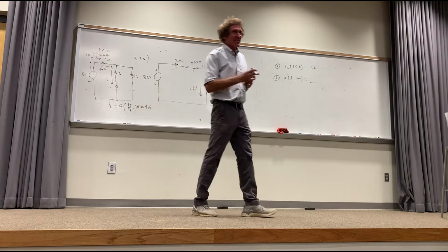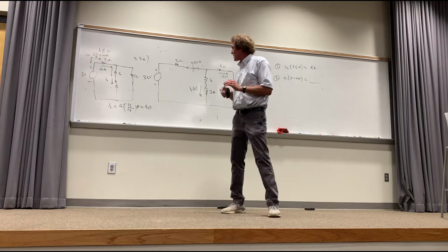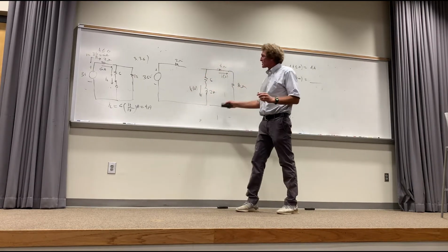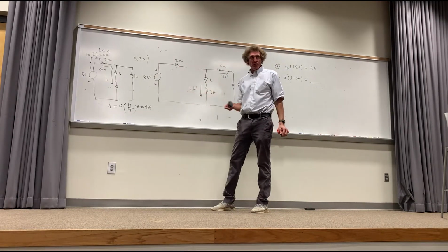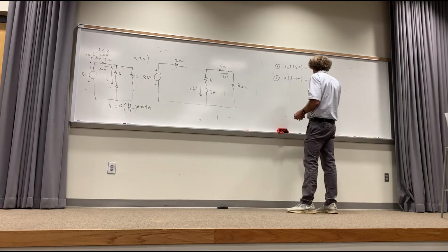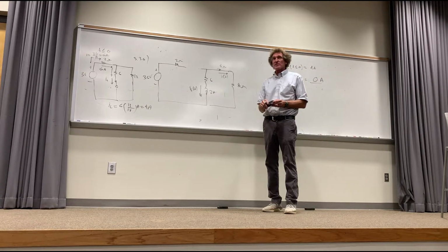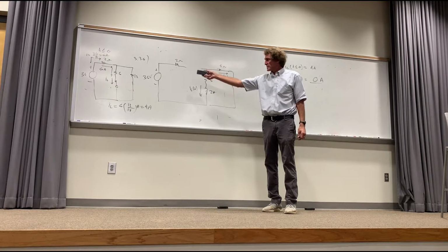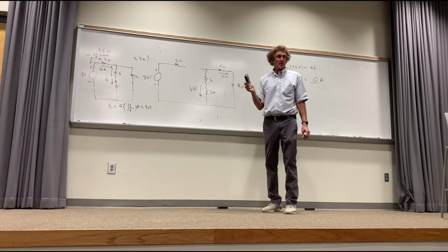I don't care. Do you have a question? Now, what is it at infinity? Well, at t greater than 0, this blows away, right? Do we have any sources in the circuit then, class? No, it's disconnected. There's no path for current to flow through that 36 volts. Effectively, it's out. So I know that IL as t goes to infinity is 0 amps. Now remember, this is t greater than 0. You all see what I'm doing here? That circuit is open, so that 36 volts has no effect on this. The only way it does is that current can circulate through it. Can you all see that?